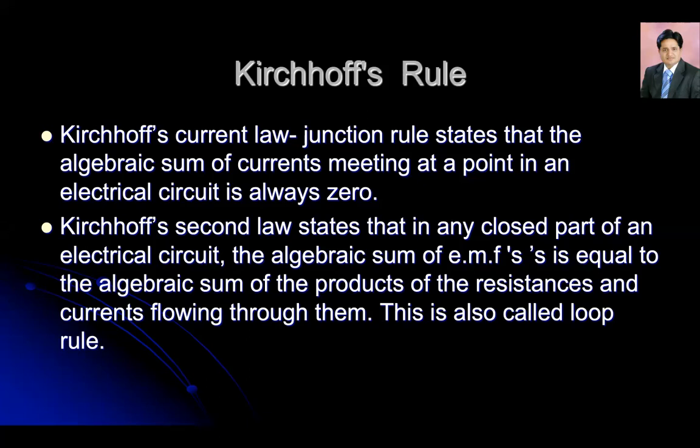Just to give you a hint, what is EMF? It is the voltage of the battery when no current is flowing in the circuit. So technically, if you have a battery and you just connect it to the voltmeter, the voltage that you get, that's the EMF. And what is terminal voltage? If you are drawing current from the battery and still you are measuring the voltage, so technically there is a resistance involved and still you are measuring the voltage, that is the terminal voltage.